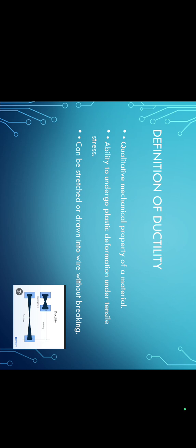In general, ductility is of interest in three different ways. First one is for a metal working operation, indicating the amount of deformation that can be applied without failure. Second one for stress calculation or prediction of severe load, indicating the ability of a material to flow plastically before fracture. Third one for indication of any changes in heat treatment or processing condition in metals.